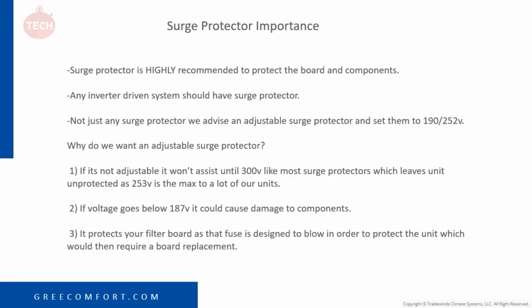All right, now let's go over the importance of the surge protector. Surge protectors are highly recommended just to protect every component on this inverter-driven system, from your compressor to your condenser fan to your EEV. Anything that's controlled by DC voltage is highly susceptible to power surges. So that's why we want to have a good surge protector on there.